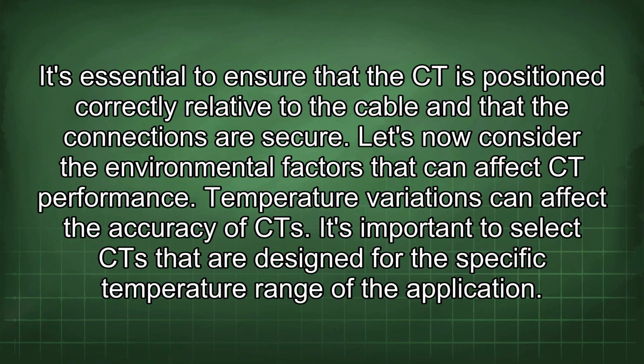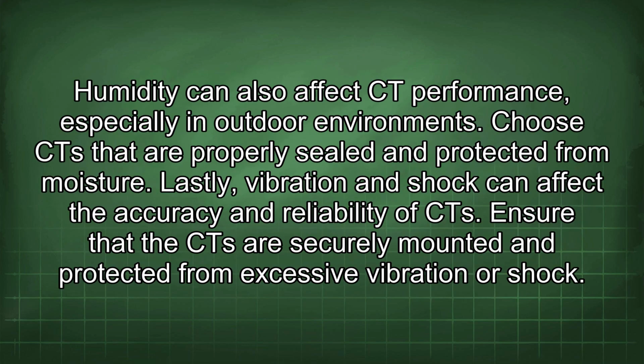Temperature variations can affect the accuracy of CT. It's important to select CT that are designed for the specific temperature range of the application. Humidity can also affect CT performance, especially in outdoor environments. Choose CT that are properly sealed and protected from moisture. Lastly, vibration and shock can affect the accuracy and reliability of CT. Ensure that the CT are securely mounted and protected from excessive vibration or shock.